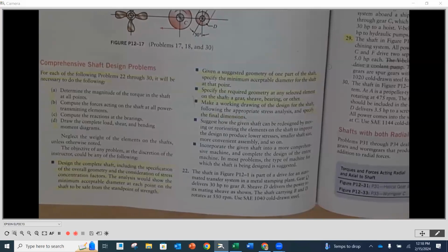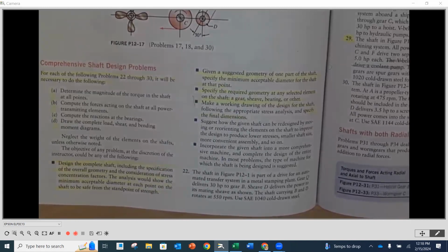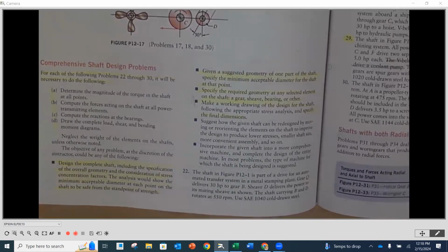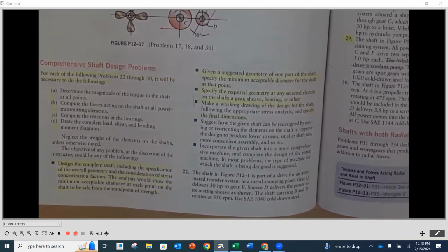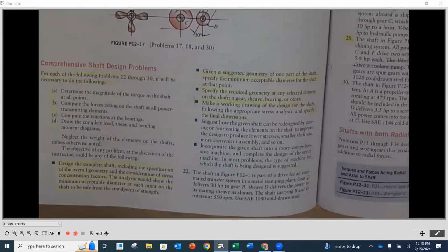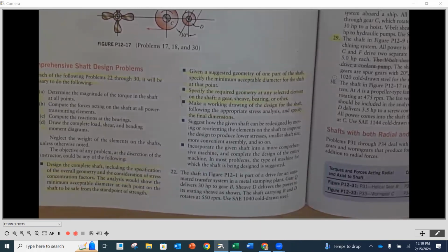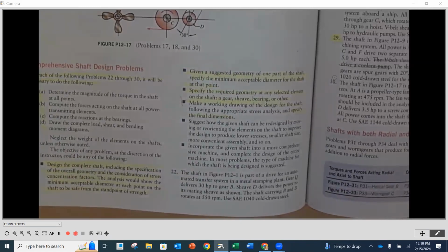We're just going to go exactly to the point that we did for each one of our examples. We just want to make sure that we have the minimum shaft diameters and what we anticipate the actuals to be, bumped up to, if you would, basic numbers. So exactly the process that we have, as well as looking at our procedure sheet. But instead of starting at the very beginning, we're going to focus on the free body diagram for the front, top, and right sides so that we can get our forces oriented correctly to then go to MD Solids.